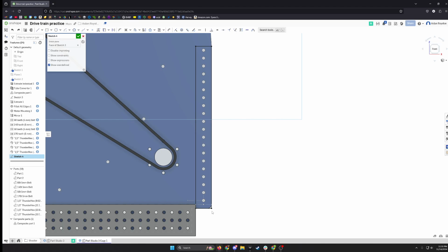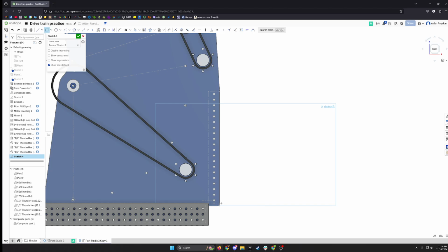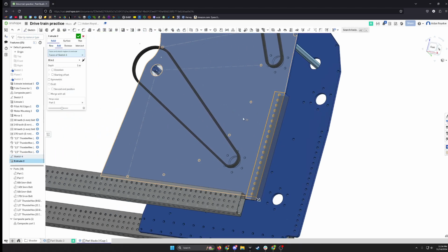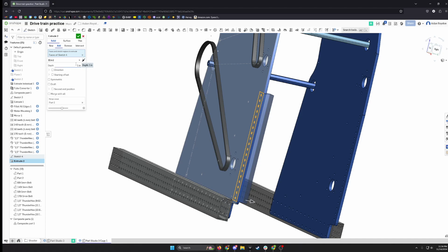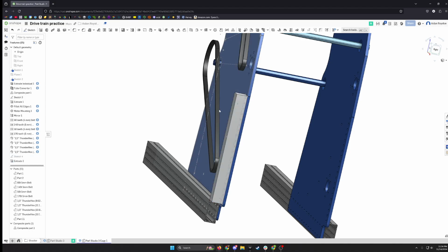That's it. Actually, you don't want it to be down here. We want to make sure it's in line here. I made a mistake there. Grab there, like that, just like that. We can extrude that. And so this is going to be a 1x1 bar. We're going to make it 1 inch, make sure it's going in the right direction, just like that. And again, make sure it's on new, making a new part.